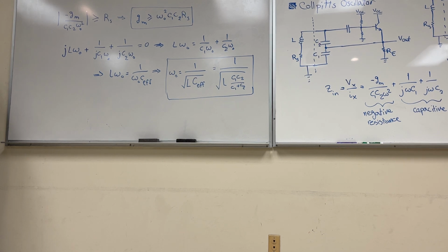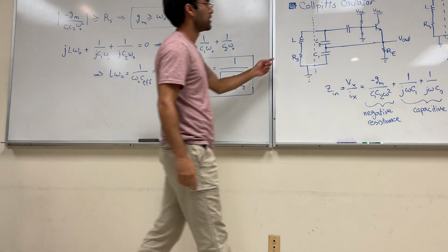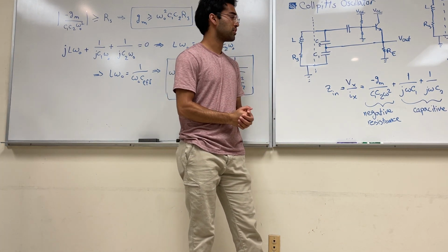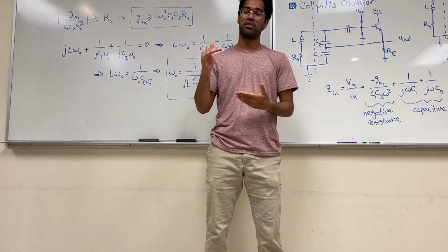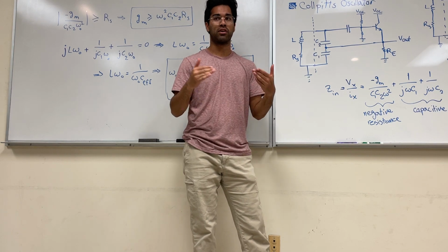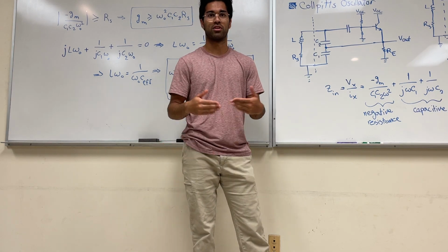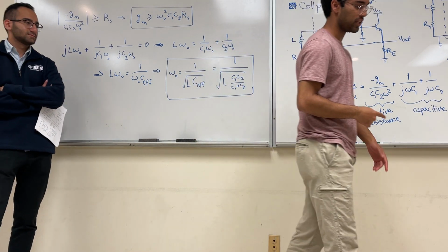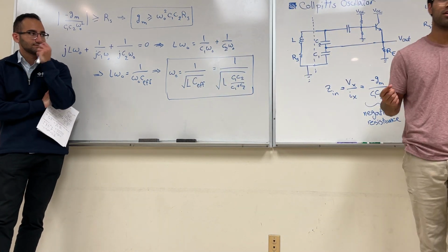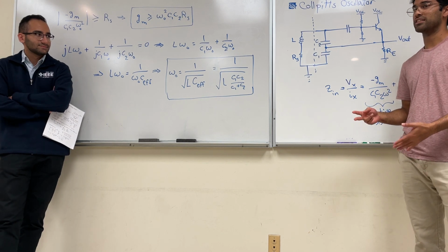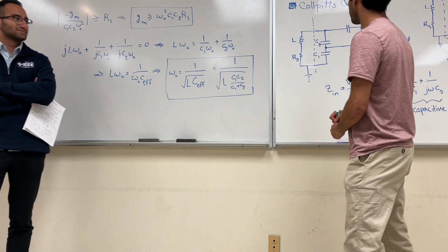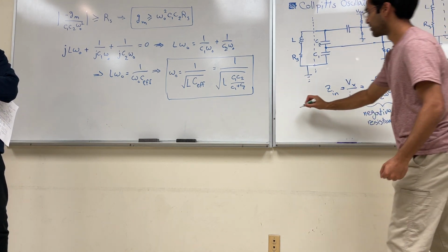But the thing is, we're taking our signal and feeding it into our transistor. And because we're feeding into our transistor, we're going to get to a certain point where the transistor can no longer amplify anymore. And that's what's called saturation. When you hit saturation, it's going to do an effect called clipping, and clipping will actually distort your signal a little bit. What turns your sine waves flat on top.